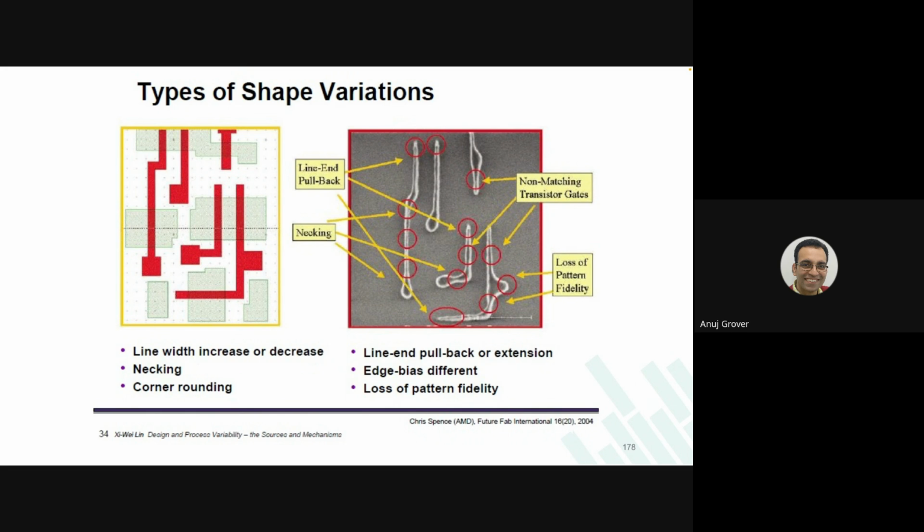So, we were talking about banked architectures, right? We said there will be banks that split our memory. Now it sounds fine: you just break the bit line here, break the bit line here, and you will have multiple bit lines available.